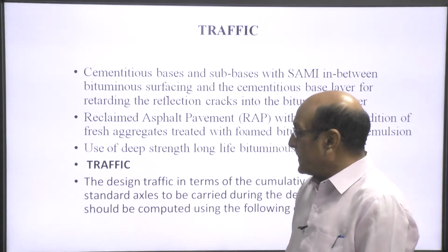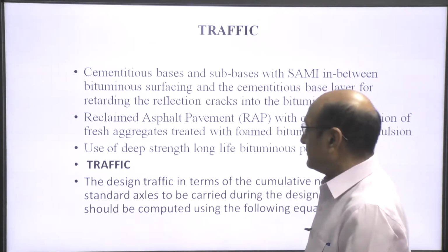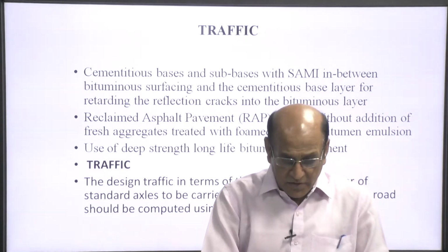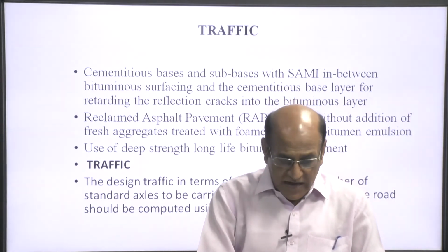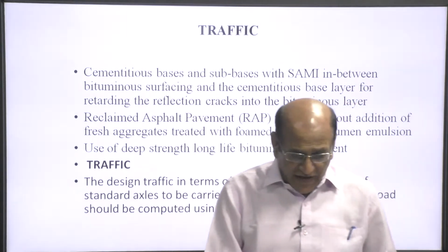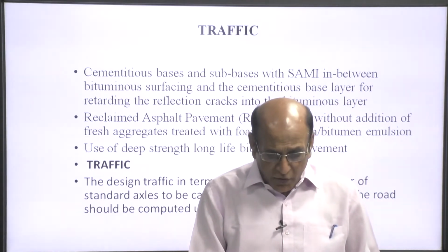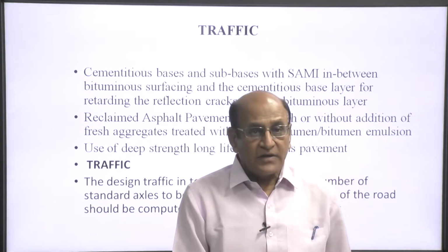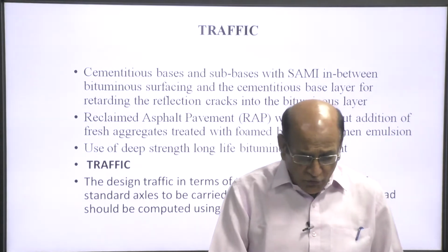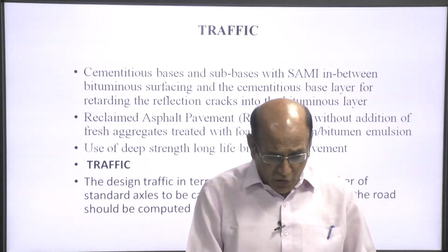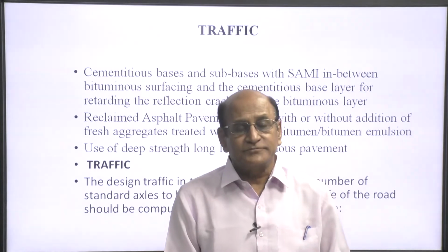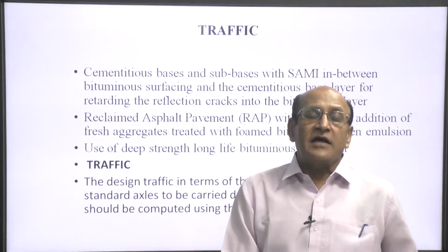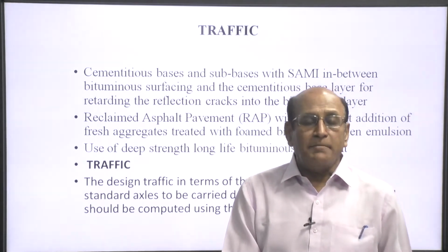into the bituminous layer. The next is reclaimed asphalt pavement, with or without addition of fresh aggregate, treated with foamed bitumen or bitumen emulsion. The use of deep strength long life bituminous pavement. So, these are the various treatments if there are existing pavements.